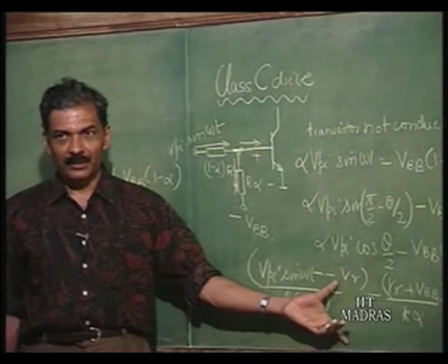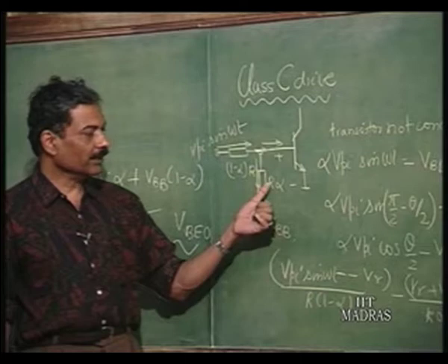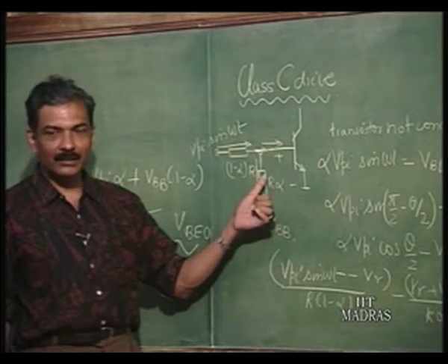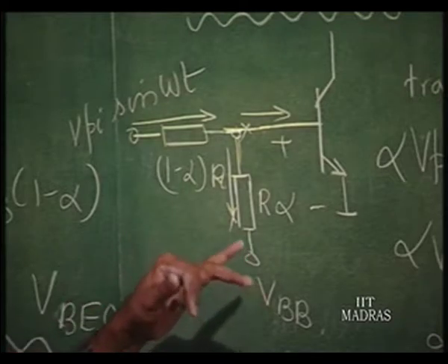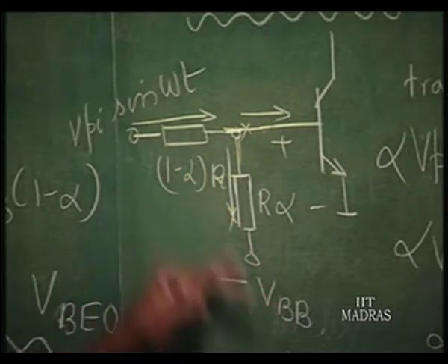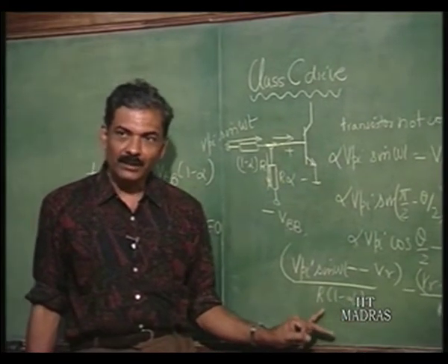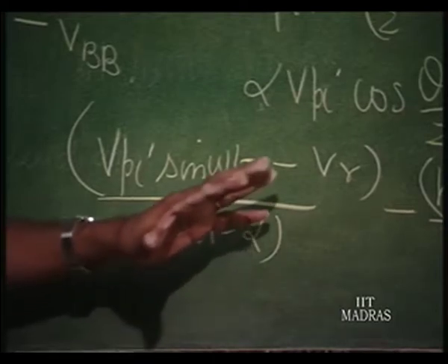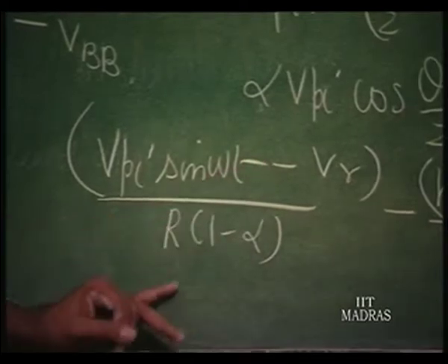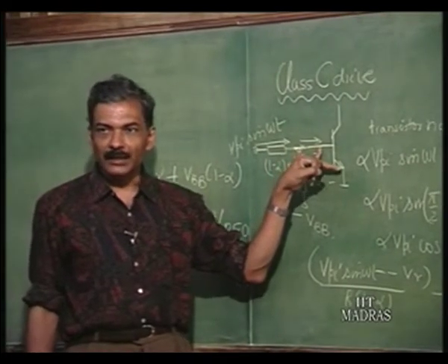And we can really use resistors here in such a manner that all these requirements are met. In fact, resistor does not come as a variable. This resistance comes as a variable only in this equation. So, that will automatically be chosen such as to fix the maximum current. This resistor is going to be chosen based on what current you want to inject as the maximum current.